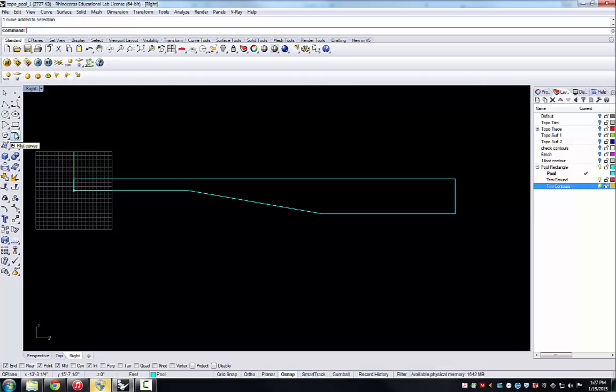We're going to fillet 2 of the curves. It is a collection of curves, so it might look odd as we do this, but we're going to use a 40-foot radius. You see it already in here. If I needed to change the radius in the command line, I would click here, and I would tell it, perhaps I'll use a 50-foot radius this time. We want a pretty big radius.